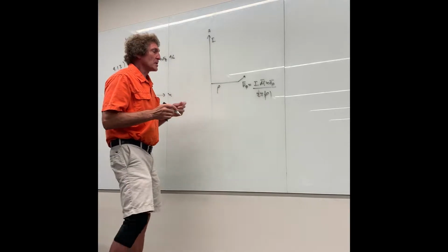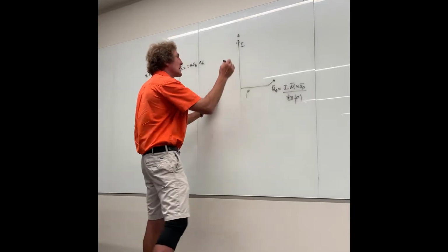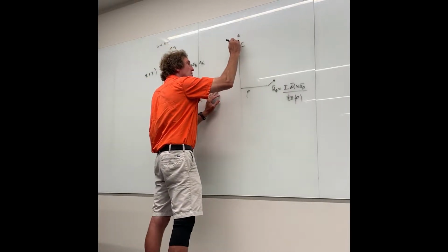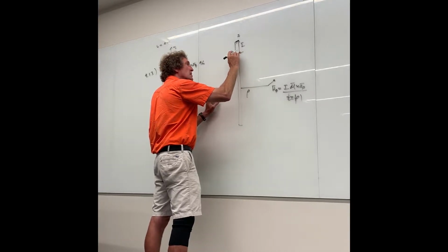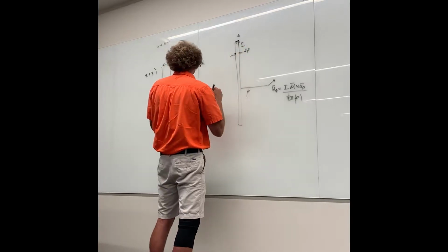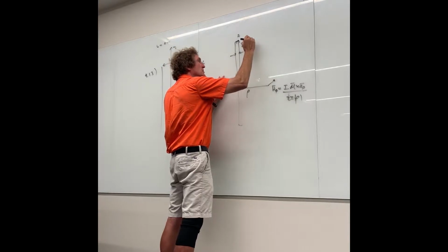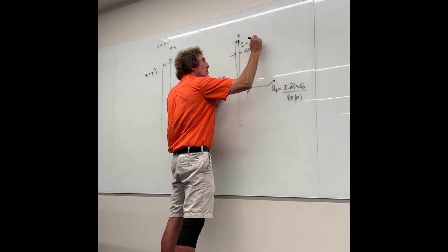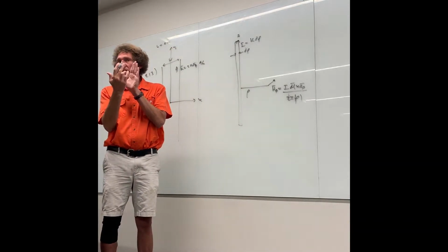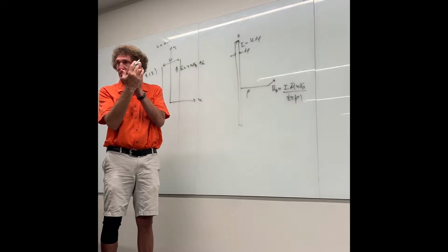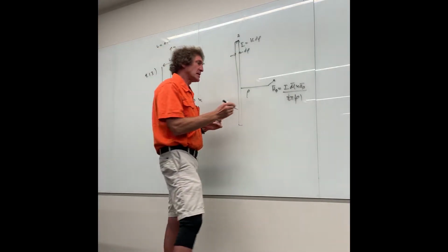That's generally true if we have a given current. If we had a thin filament of current with a thickness of d rho, in this case the thickness would be dx, then instead of I, we'd have the surface current density K times d rho equivalent to I. Does that make sense to everybody? Remember K is amps per meter. If we multiply by meters, we get amps. So we're going to have a sliver of current right there, and we're going to get the H field, but now it'll be the dH field.